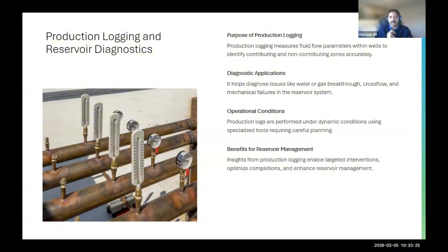Production logs are performed under dynamic conditions. That means without killing the well, you are doing these production logs using very specialized tools which require careful planning. And what you gain from it is that you will get targeted intervention, optimize your completions, and enhance your reservoir management.